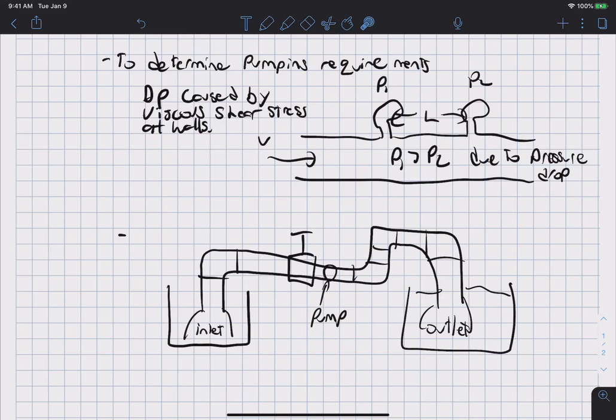Okay, well, all of these components, these elbows, and the valve, all of these components here also add losses to the flow. That is, the flow has to be turned as it goes through the elbow. That's going to introduce a delta P across the elbow. There's a delta P across a valve, especially if it's partially open. There's a delta P associated with the inlet, because the streamlines will have to go down, around, and up, and there's going to be a lot of viscous losses for that.